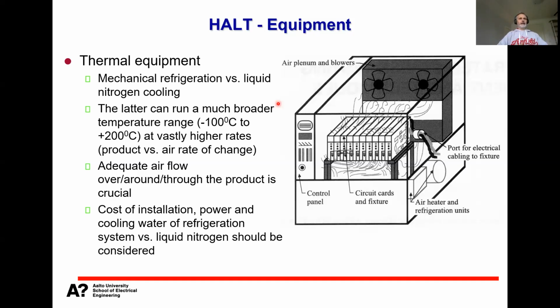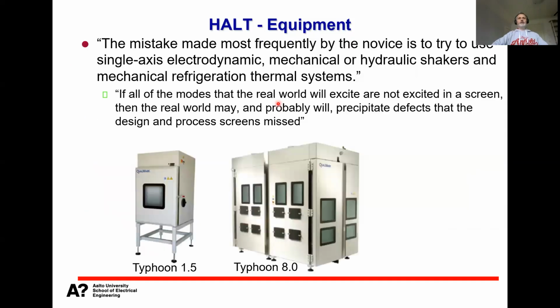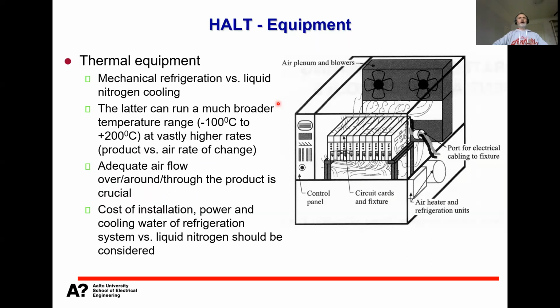And the other thing is that you need to have the installation money, and you need to have the operational, and you need to have also competent personnel to operate these kind of liquid nitrogen related systems. So that is kind of the first decision you need to make if you would go for these kind of chambers utilizing liquid nitrogen, or could you use just a normal, let's say, thermal chamber which uses mechanical refrigeration, and then you are limited with the lower temperatures and rate of temperature change.